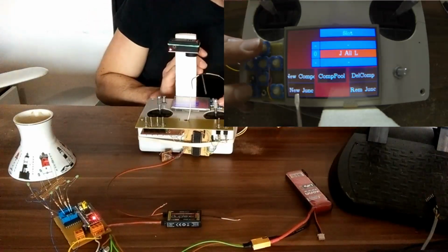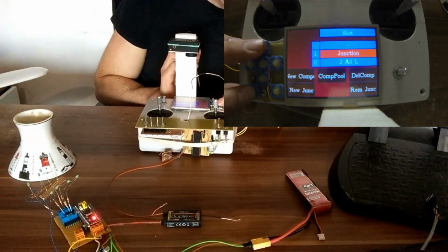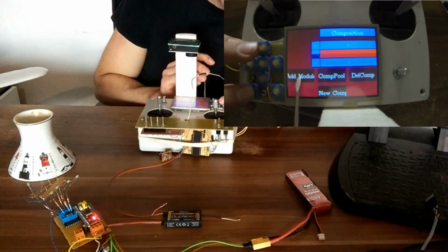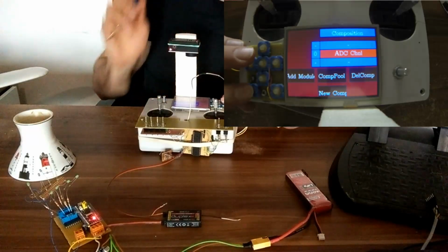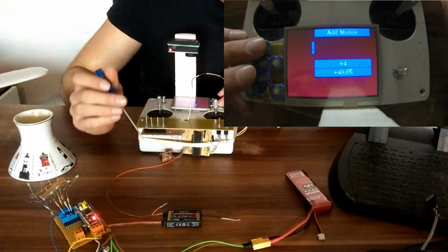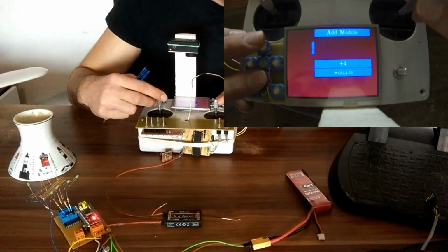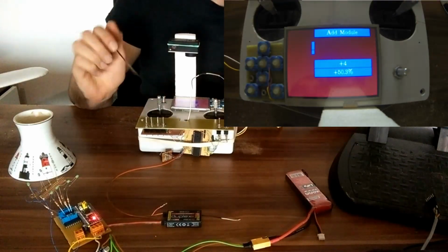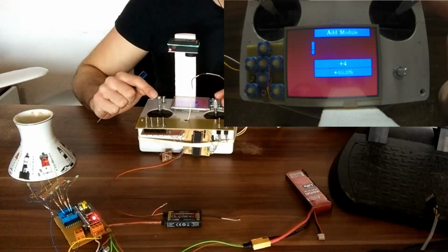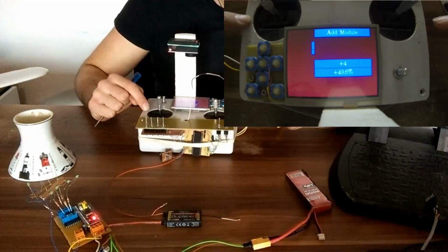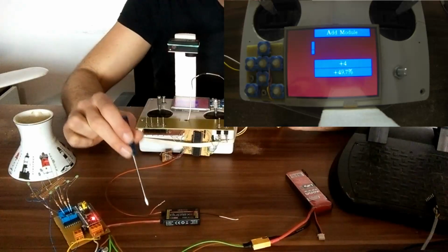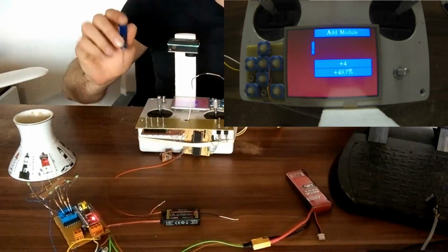So I'm setting up another junction. I'm going to this junction, placing another composition here, and another ADC input. So in this case, I'm going to set the ADC to 4. So the thing what is happening here, these sticks on the host controller are channel 0 to 3. So that means the channel 4 is coming externally via this cable. So this is the loopback I've been talking about.